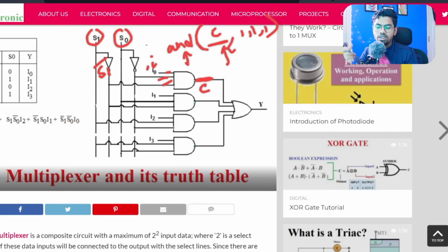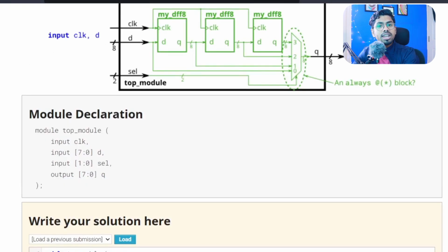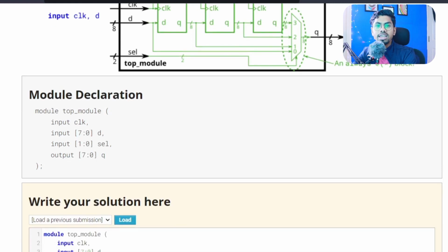In behavioral description language, what we'll try here in our example is to build this multiplexer in the behavioral domain. In gate level, for sure you can try sometime. It'll give you more insight to learn your digital electronics. But for our task today, we will go for a behavioral description. To write your multiplexer in the behavioral domain, you have 2-3 different ways. One could be using if-else conditions, or you can use a case condition, and I guess case is more readable. So as a beginner, it's better to start with a case statement, right?